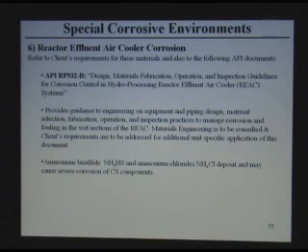But if you don't weld it properly, you end up with cracking. I have experience with a duplex air cooler, which failed after 1 week of operation. It went through in 1 week, and we had to scrap it, buy new ones and shut down, a big loss. So the corrosion here is due to ammonium bisulfide and ammonium chlorides, and as you inject water to remove them, they create some corrosive environment.